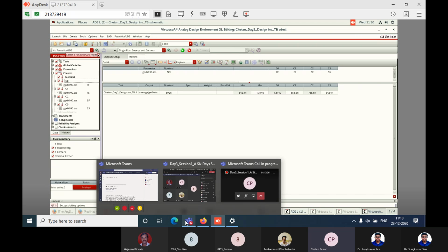Waveform, beside AD, right hand side. Good. Now click on P, your output. Click on that. Right click. Send to calculator. Good, good. Now you calculate the delay function. You just search for delay.